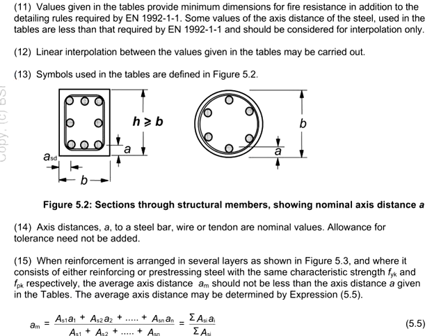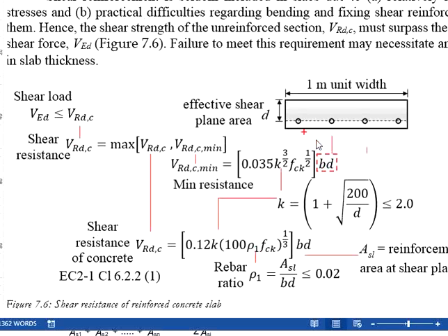That's why Eurocode provides you a diagram, something like this. In their definitions, asd is referring to the side of the member, whereas a is referring to the soffit. In the case of the slab, we have only a, but not asd.